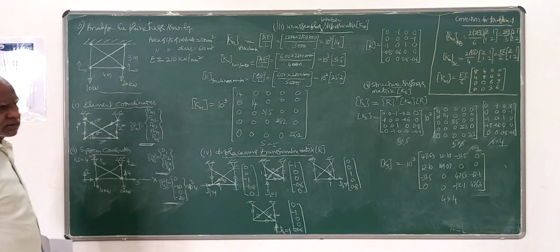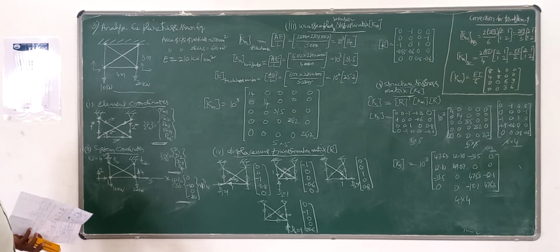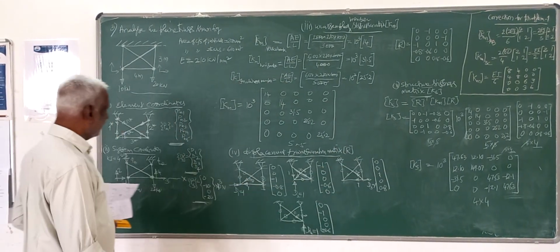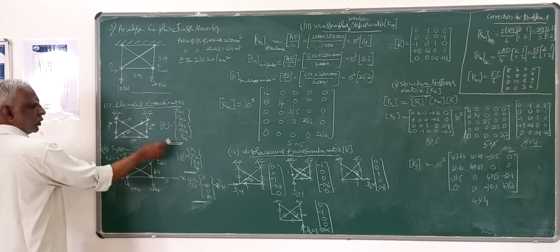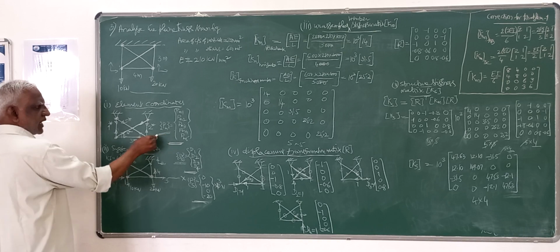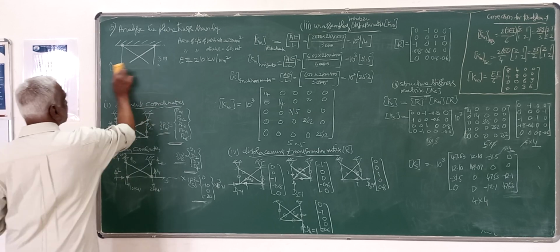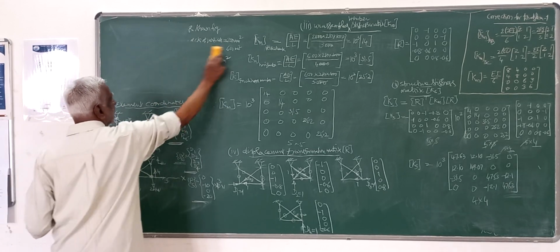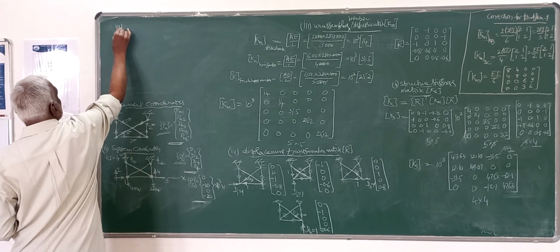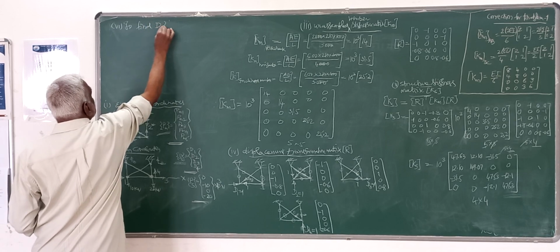The stiffness matrix is that in the global direction. Then we have two steps left, the 6th and 7th steps, where we determine the unknowns. In the 6th step, I will determine DS. In the 7th step, I will determine PM using the standard equation. Then the problem is completed. So the next, 6th step, is to find DS.